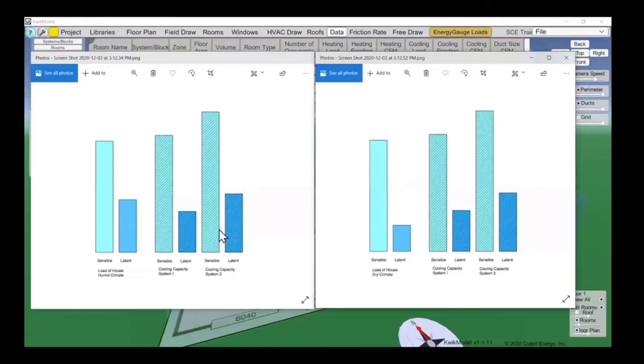So that's an extra step that you have to do in a humid climate as opposed to California or a dry climate. We look at, here's our sensible and our latent load. We measure our sensible, and that looks good. And our latent is also good, okay? Because this relationship is fairly stable on capacity, but in a dry climate, this latent load is usually really, really small compared to this. And 99% of the time in a dry climate, when you pick an air conditioner that meets the sensible load, it will also meet the latent load.